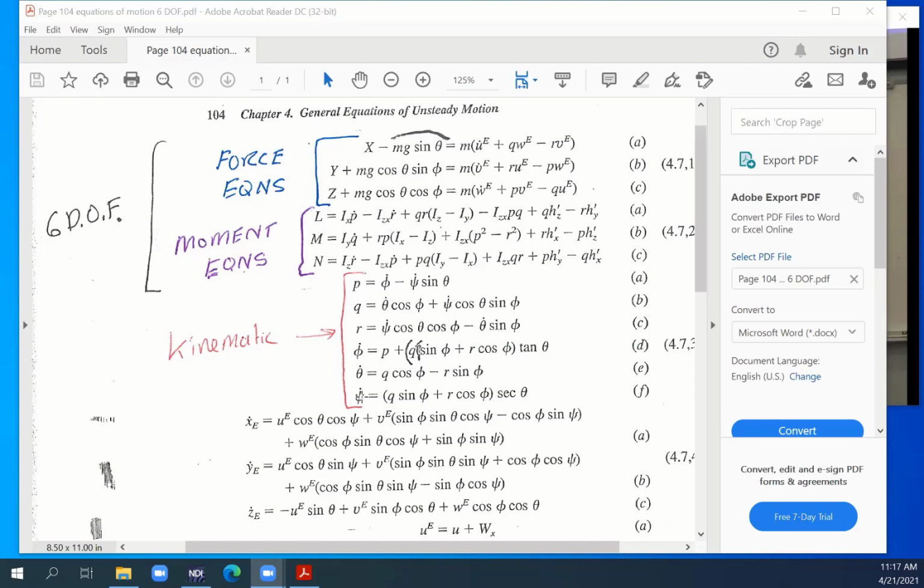And that's numerical integration. And that's exactly what X-Plane does. It uses the equations of motion and a pretty complicated aerodynamic model. And then it takes your elevator, aileron, rudder, and throttle, flaps, and all of the other inputs into the equations. And it says, okay, I'm sitting on the runway still, ready to take off. And then you kick the thrust up and take the brake off. So that creates a net force forward. And it jumps forward 1 time step, and the airplane moves a little step down the runway.